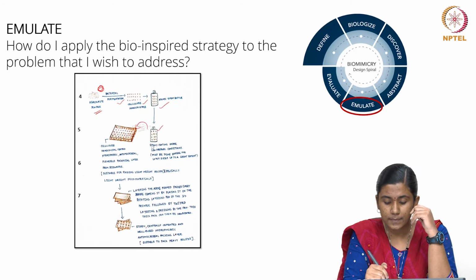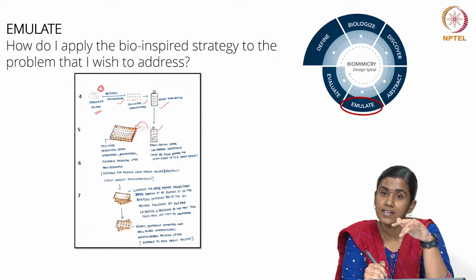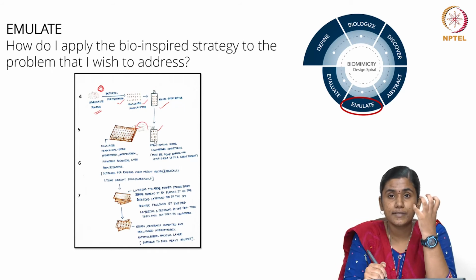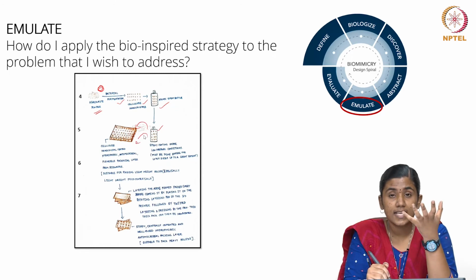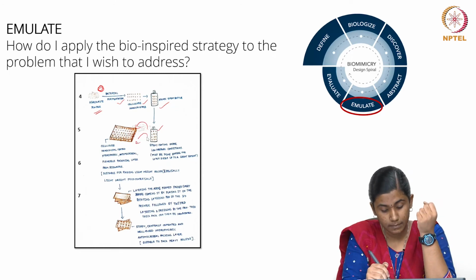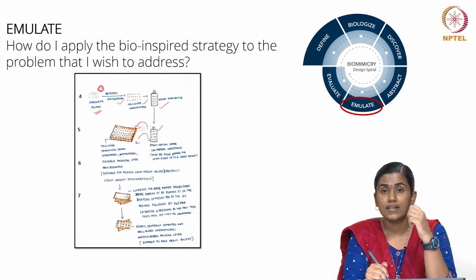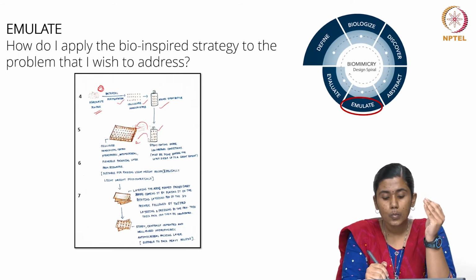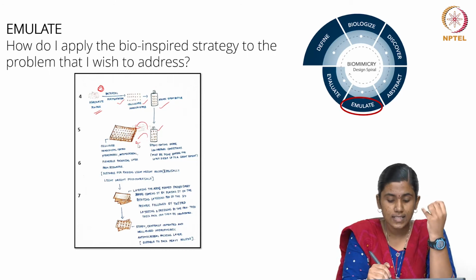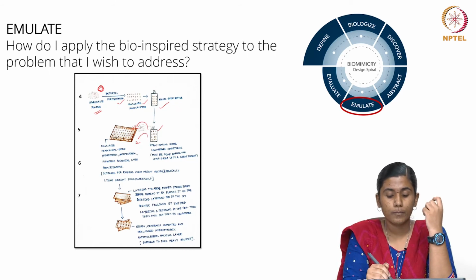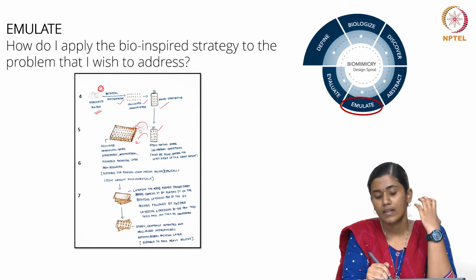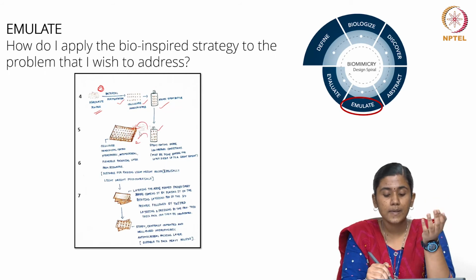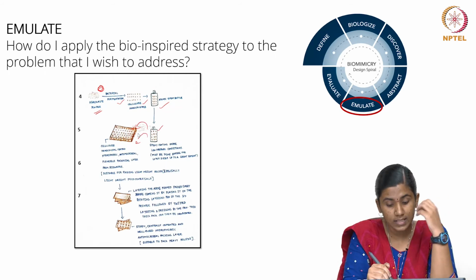And the important step is that this spray coating must be done before my layer entirely dries up, else my nanocrystals won't get fitted properly onto my layer. So once these nanocrystals are coated and my layer has dried up with these nanocrystals in place, I am able to get a whole packing material which is flexible, resistant to external impact, antimicrobial, and hydrophobic in nature because of the presence of these nanocrystals, and it helps me in putting perishable items within this pack material.